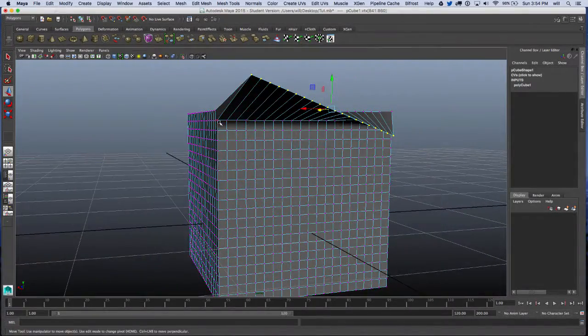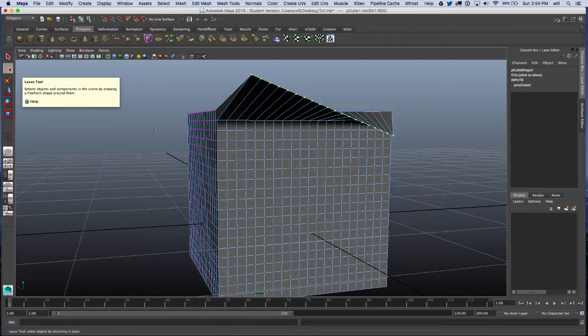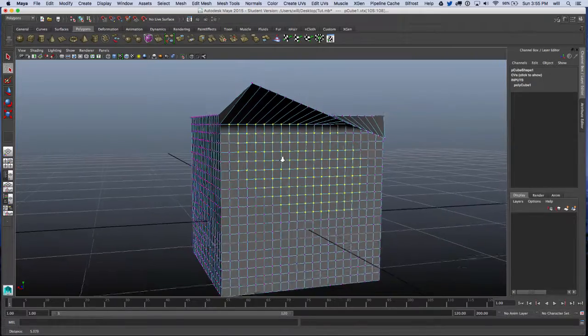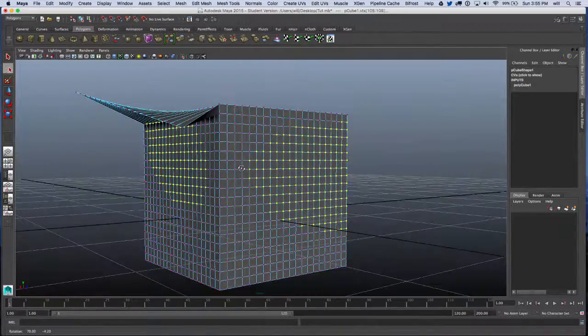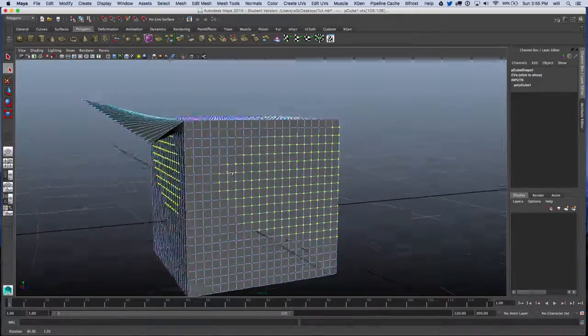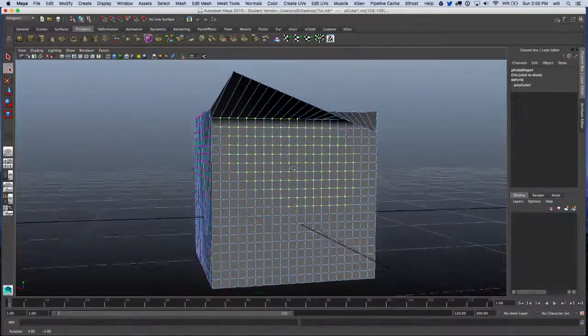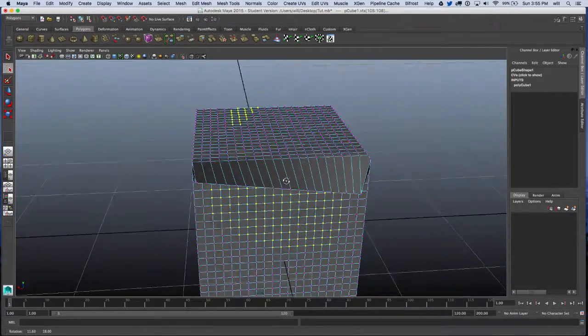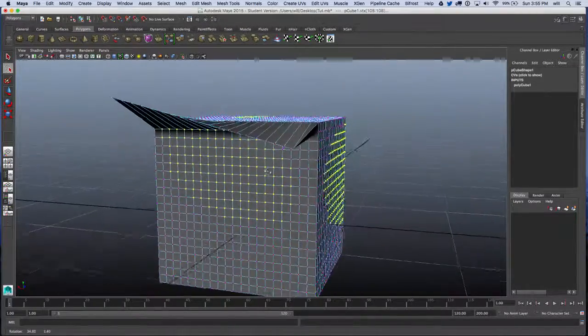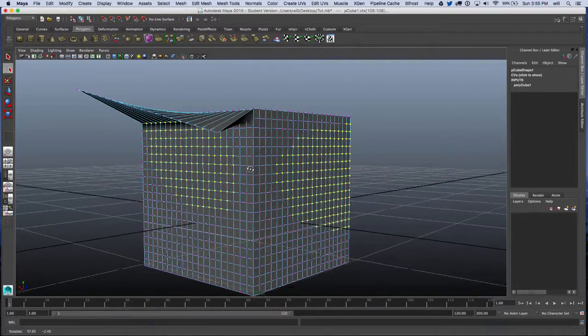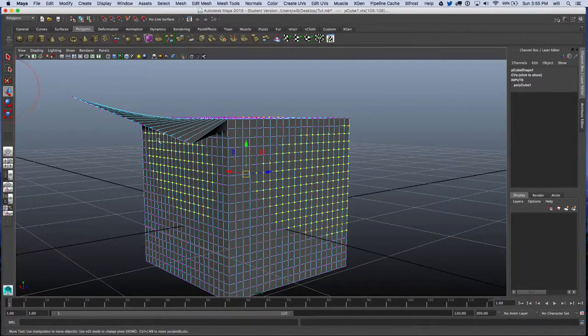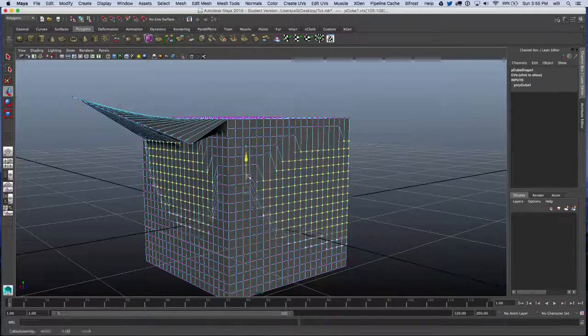We can also play with multiple of these. So we can use the selection tool, which is the lasso select. If I just hover this, it'll tell you the lasso tool. And I can select multiple of these vertexes. Now, be careful, because if you do, you can see it selects the whole way through the object, everything that you were looking at before. So be really careful to do that. So you have to find a view that you can select multiple of those objects. And this always happens when you're playing around with object moving stuff.